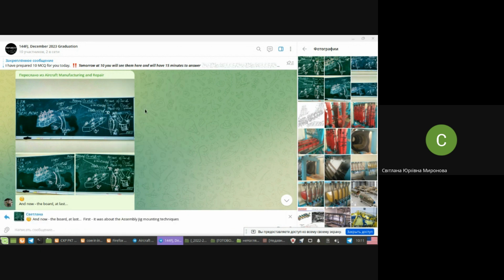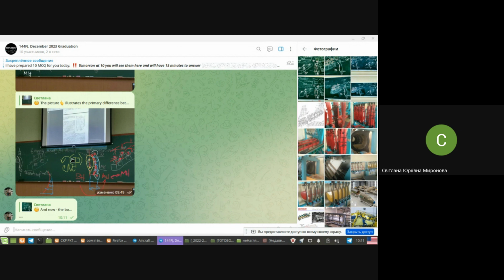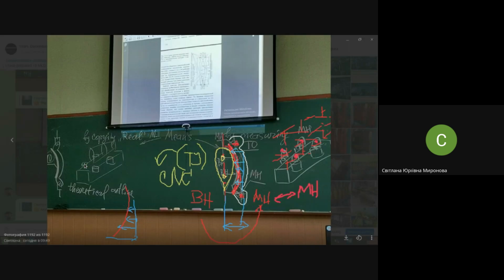How we're going to measure position of contours in each particular locator, and next, how we're going to measure position of these connectors in the skeleton of the jig in order to hang locators to these connectors and obtain the position of the system of locators with correct coordinates. All these techniques used to be called coordinate techniques, coordinate template method, for instance.